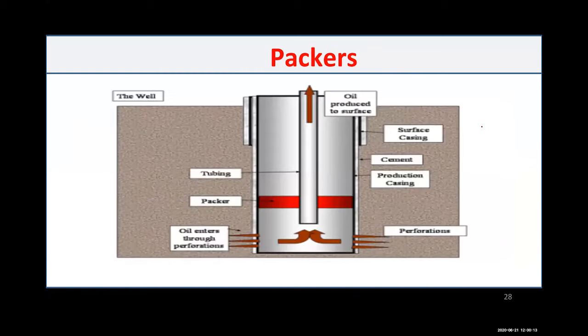A second one is a packer. In this case, you set the packer in the zone that you would like to treat and treat it, then release the packer and go to another section and treat it, and keep going section by section for the treatment.